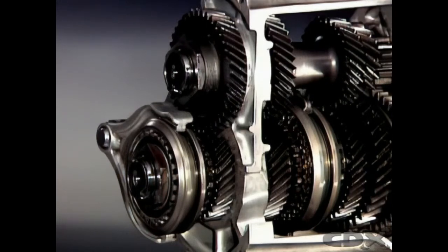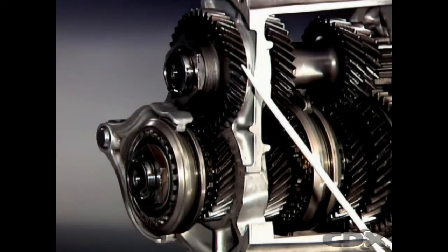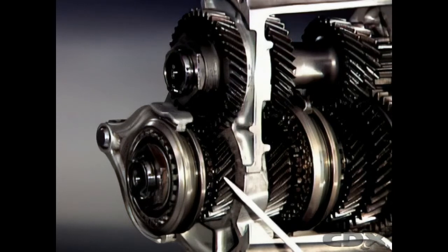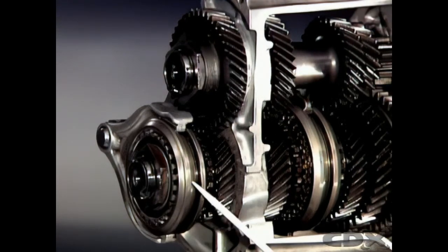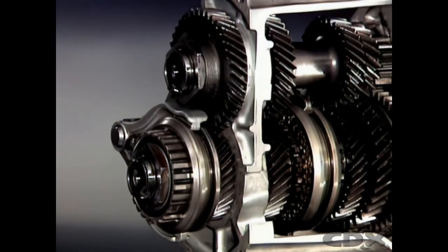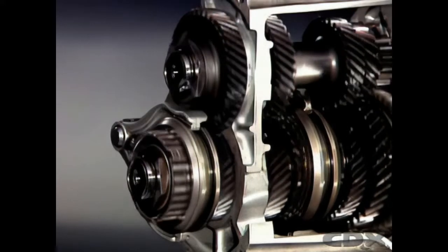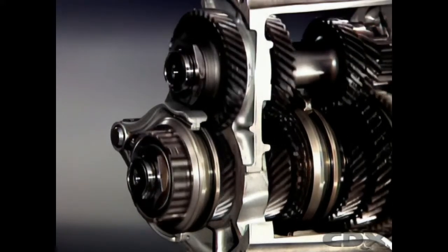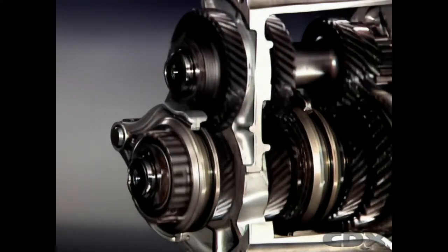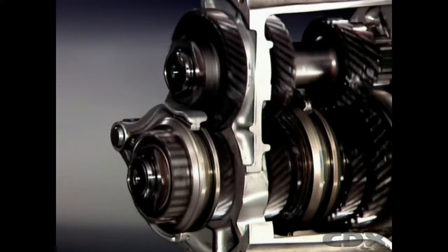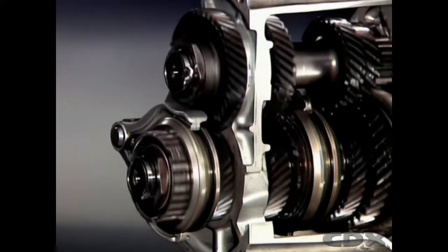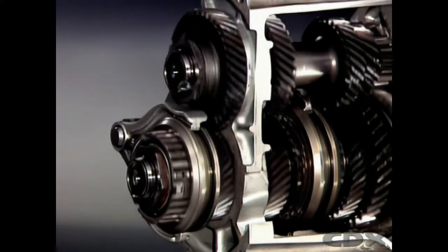A 5-speed transmission has an extra fixed gear on the primary shaft, meshed with a mating free gear on the secondary shaft. The free gear has its own engagement sleeve and synchromesh unit beside it. Selecting 5th gear locks the gear to the shaft. The gear on the primary shaft is larger than the gear on the secondary, so an overdrive ratio is provided. The secondary shaft rotates faster than the primary.